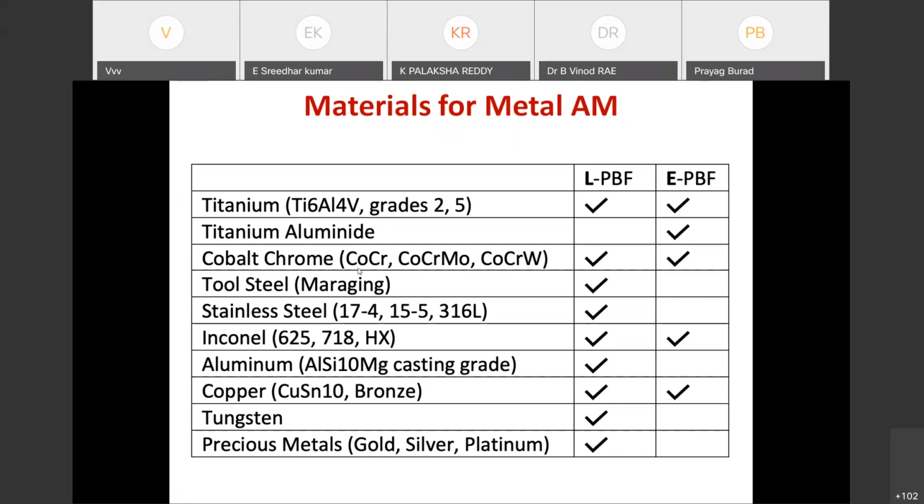Generally, knee joints are largely produced with cobalt chromium because of its high strength, but it has high density also. So the implants produced with cobalt chromium will have more weight compared to the titanium one. Depending upon the requirement, the knee joint is largely produced with cobalt chrome. For the rest, either hip joint or any craniofacial and maxillofacial or customized implants, largely titanium is used.